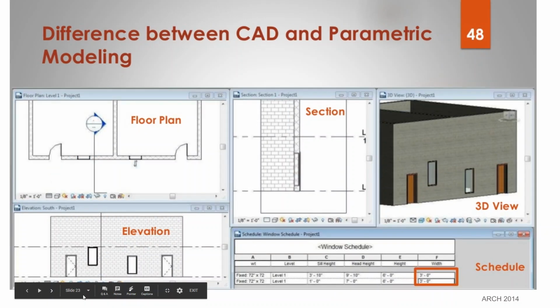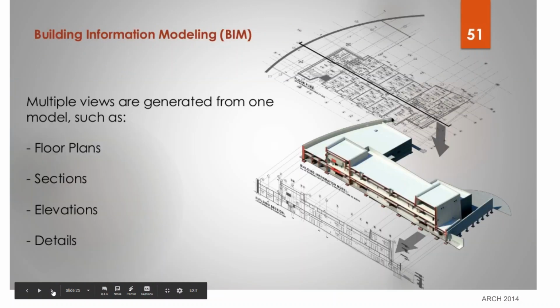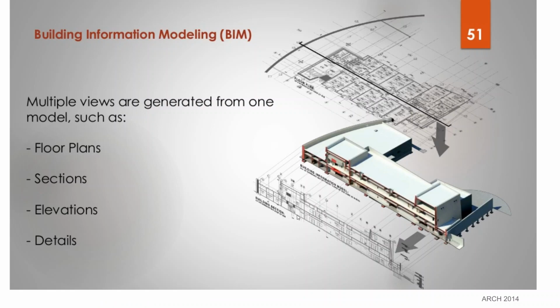And we can change the size of that window parametrically. That automatically updates all the way through to details on our spreadsheet. So this is a nice little animation of a larger project, but suffice it to say, what we've looked at is we create the model, and all of the geometry of the model can be represented in two-dimensional forms for us. Much of the work that architects do to create construction documents.